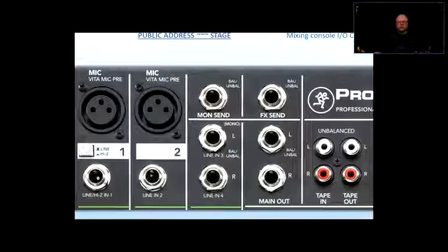Now mixing boards are supposed to be the most versatile things because you never know what instrument you're going to deal with, who comes with what, and what situations you're going to use it in. So the better the mixing board is, the more options it's going to have for what you can plug into it, right? So you can have a 1/4 inch input here, or XLR. In this particular mixing board, it's mechanically arranged so that once you plug into the quarter inch, it mechanically disconnects this XLR input here. Okay.